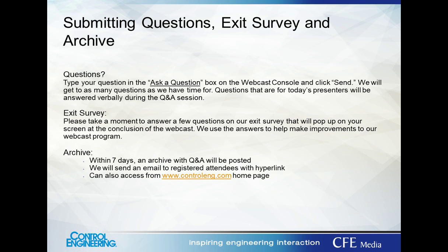And one reason it's important is not only because it's a core element, probably one of the best things you can do in single loop APC, but feed-forward is also kind of the equivalent. It's the single loop version of model-based control, is how I look at it. It's a valid comparison. So once you understand feed-forward, it'll help you understand multivariable, multi-loop model-based control as well.